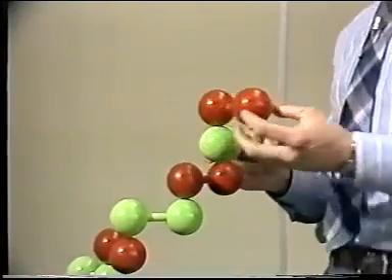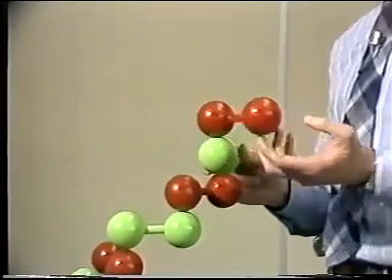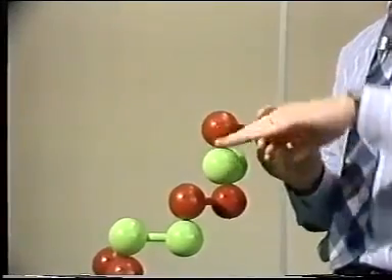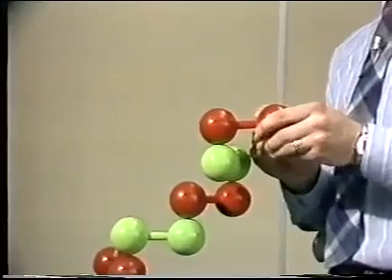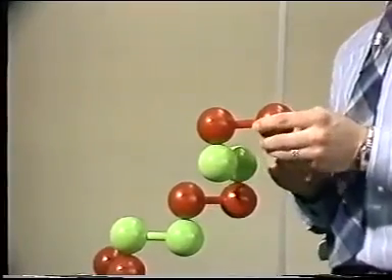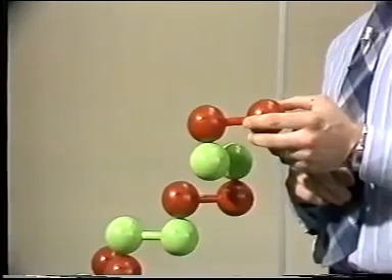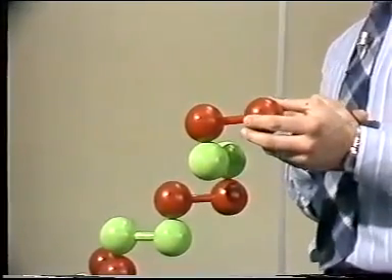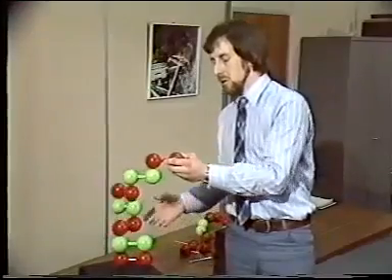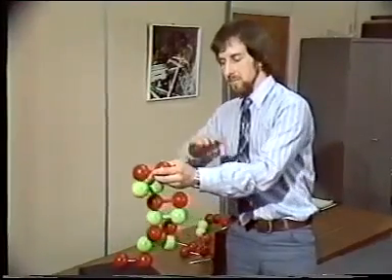Well, it can rotate in yaw angle, but it cannot pitch up and down or roll. It is restrained. So we have in fact lost 3 degrees of freedom with this special geometry. And now every link will only move in parallel planes.